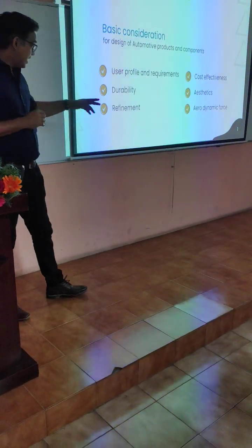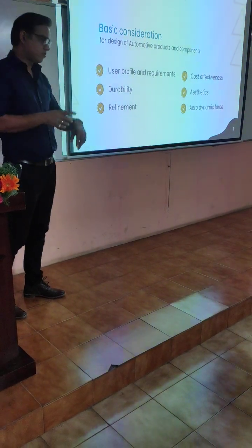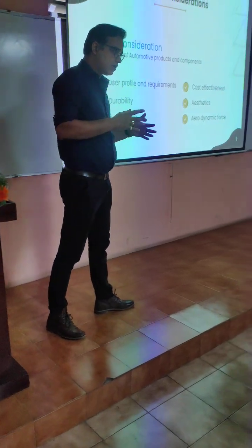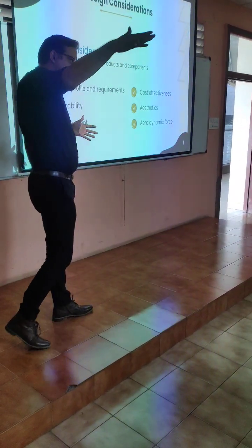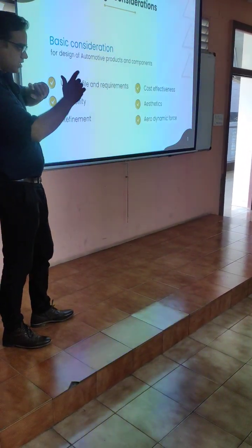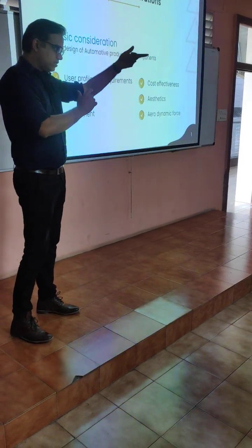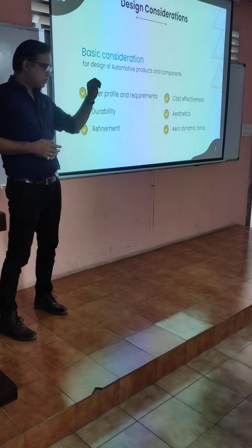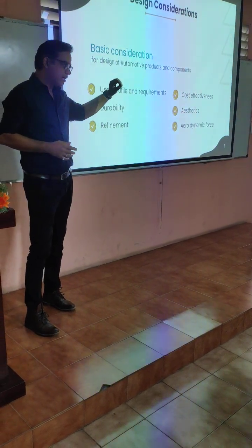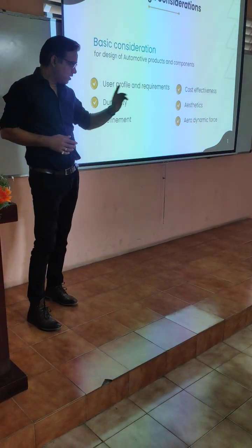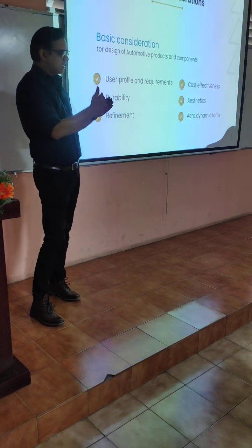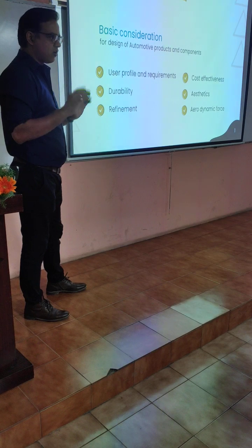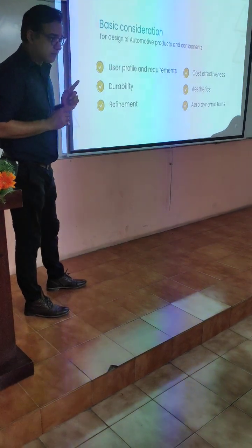I'll talk about that later also, but we do stack up. The vehicle is a stack, right? One component sits over the other, sits over something else, so it's a stack. If you don't do damping at every point, a plastic sitting on a metal with a hard bolting will not make any noise that you can even hear.